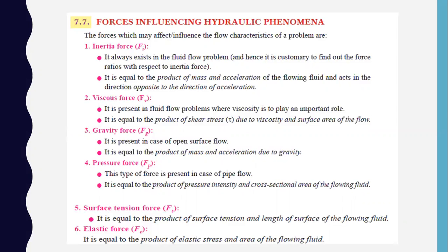This is present in fluid flow problems where viscosity plays an important role. It is equal to the product of shear stress due to viscosity and surface area of the flow. The next one is the gravity force. It is present in case of open surface flow. So in most open surface flows, gravity forces will be available. It is equal to the product of mass and acceleration due to gravity. So here, the difference between the inertia force, that is M into A, and gravity force, M into G.